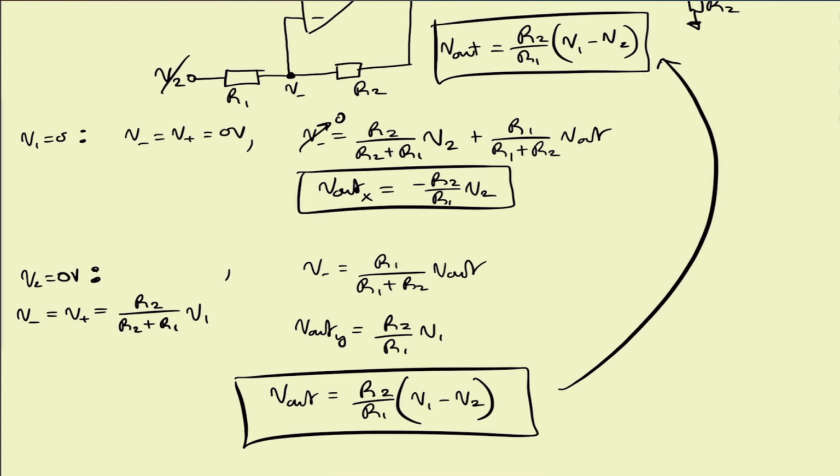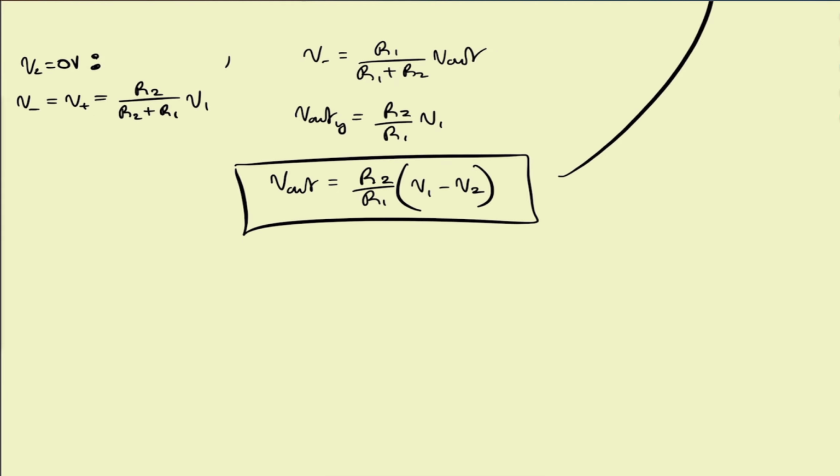So now that we know that our gain factor will be achieved by R2 over R1, we can then go ahead and find, well, not find, just pick two resistors of 5% tolerance.